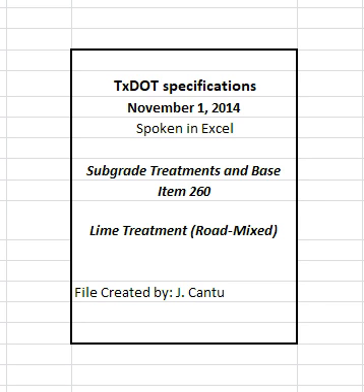Shape existing material in accordance with applicable bid items to conform to typical sections shown on the plans and as directed. Unless otherwise approved, proof roll the roadbed in accordance with item 216, proof rolling, before pulverizing or scarifying existing material. Correct soft spots as directed.